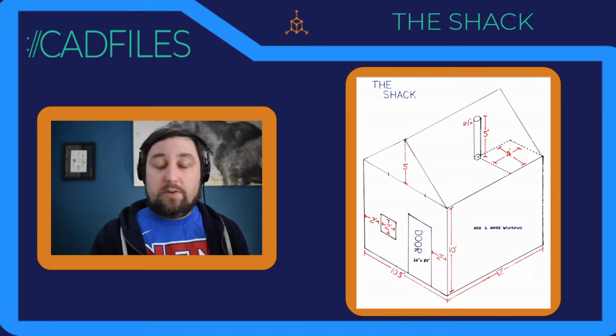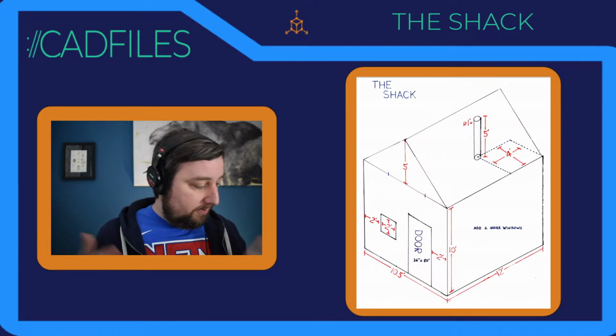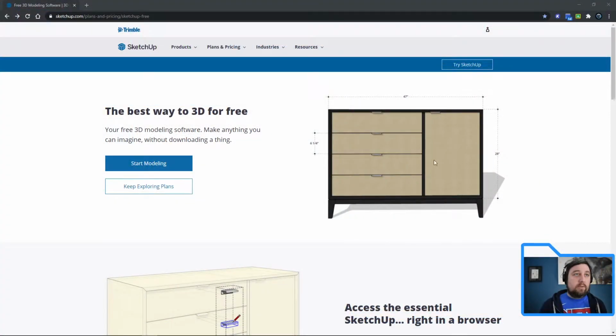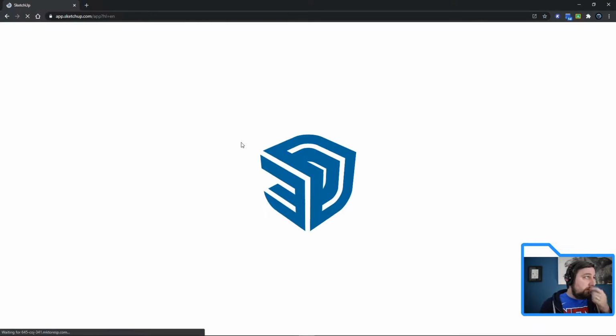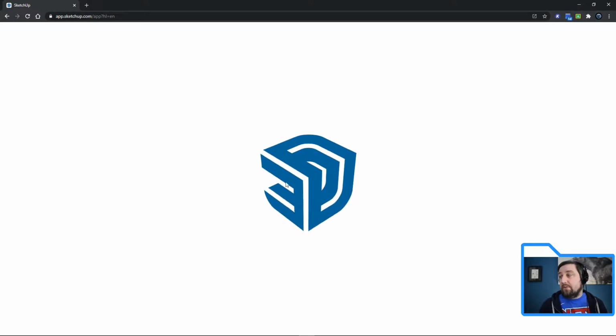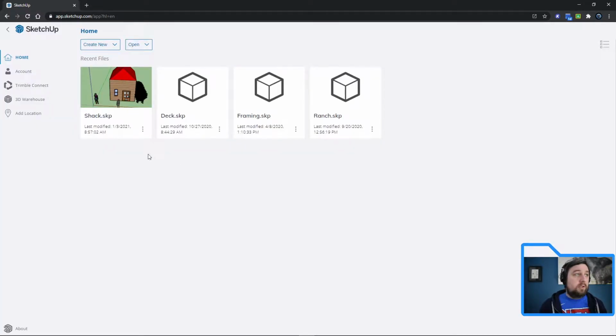You should start off by Googling SketchUp Free or following the link on the classroom page, and then making an account. Up top here, of course, it's covering my name, but log in, make an account, use your school credential, school email, and click Start Modeling. This will come up. Obviously, it's loading. They got a new logo. It's ugly. But up top here, create new. Simple template, feet and inches is fine.